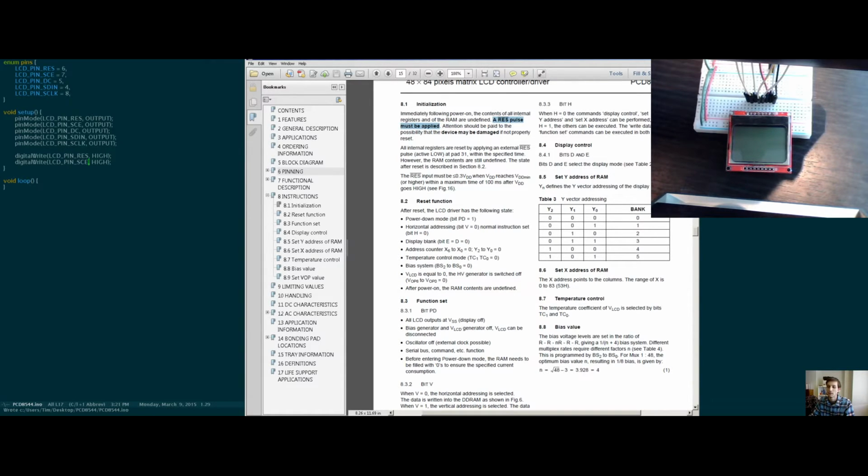So after we send that pulse, all of these internal registers and the RAM get explicitly set to certain values. So to send a reset pulse, what's a reset pulse? We need to figure that out. A pulse is generally when a line changes from low to high and back to low, or from high to low and back to high.